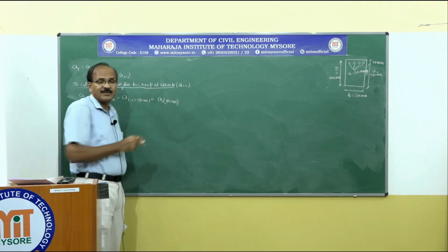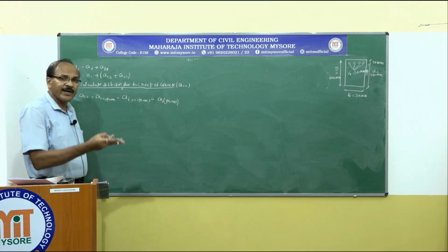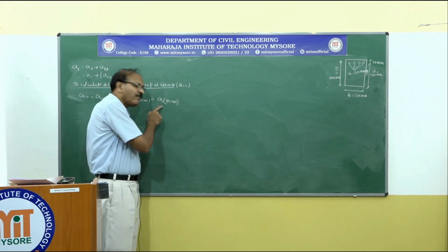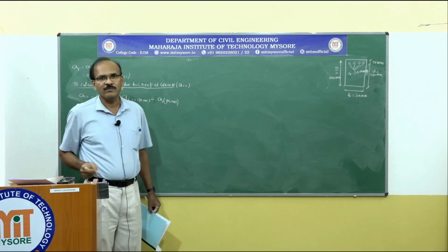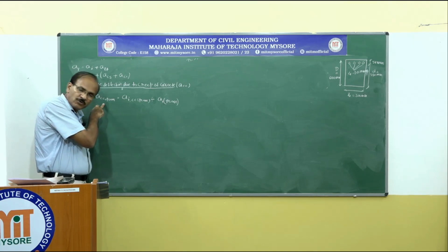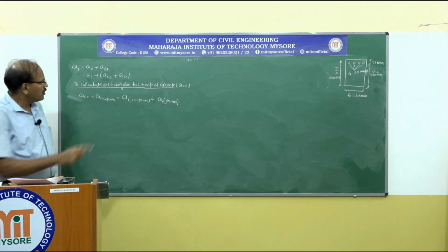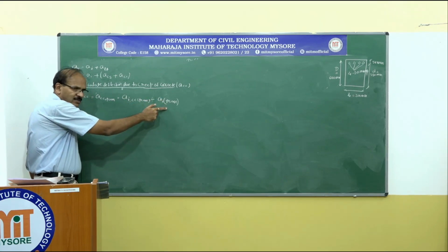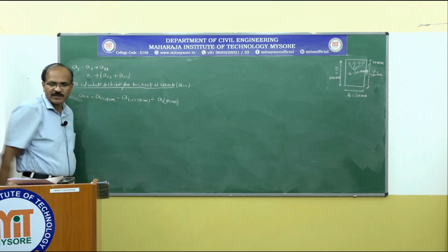Next, AI permanent. Once we have that total deflection due to immediate and also due to creep, we have to take out the immediate deflection due to permanent load to get the deflection due to creep of concrete under permanent load. So now we need to find out this first, and this one next. Deduct this from this to get this, and put this value here to get the total deflection.